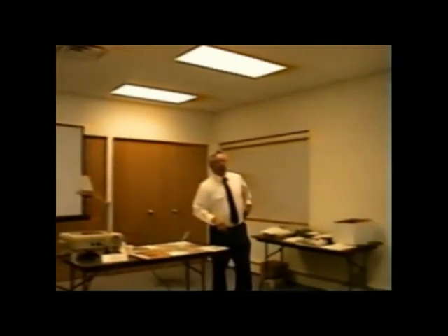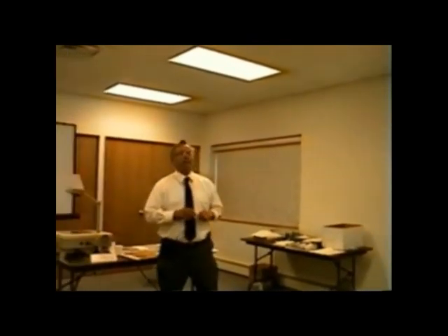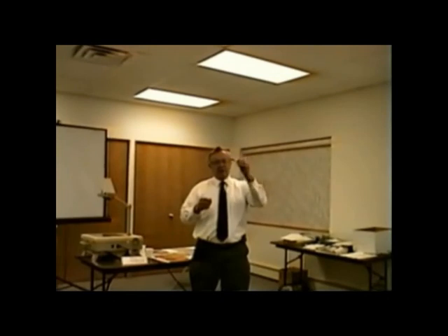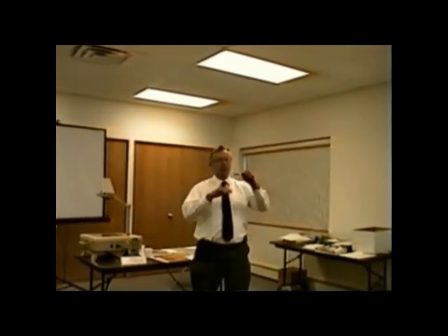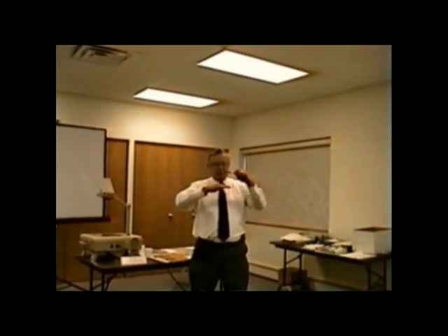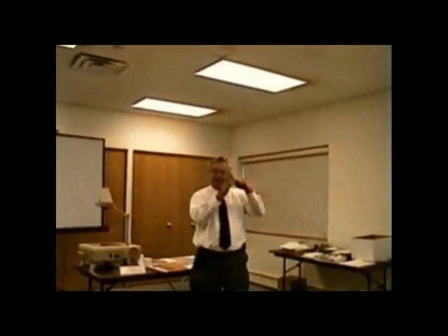Let's stop now and talk about that. That paragraph was incorrect. Today's boards, I got to tell you, they're talking about keeping the flame on down to 0.2 of a microamp. First of all, we have a flame rod. And just a quick review, if we have a flame rod and we have a burner at the bottom, when we have ignition, we have fire that goes up and connects the flame rod.